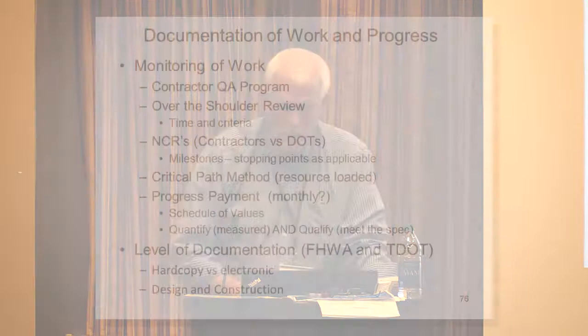As an example, on the flip side, if you have environmental concerns, require that as part of their schedule submitted to you, just where those environmental commitments will be incorporated into that phase of work. In other words, don't assume. If you want it, get it in there, and that's your line in the sand to help spot check the contractor that they're actually providing what you ask them to do.